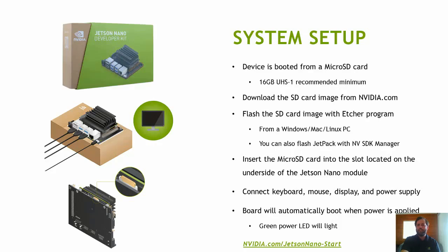Okay, next let's walk through setting up a new Nano dev kit out of the box. The dev kit boots from a micro SD card, so all you need to do is download the SD card image from our website, which already includes all of the Jetpack components, and flash the image to your micro SD card from any PC that has an SD card slot.